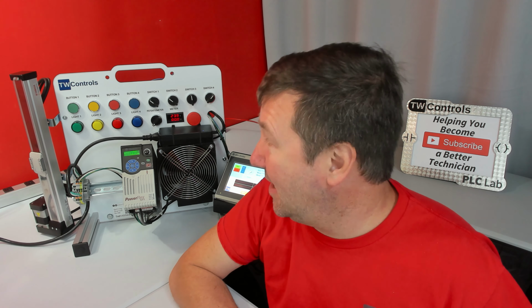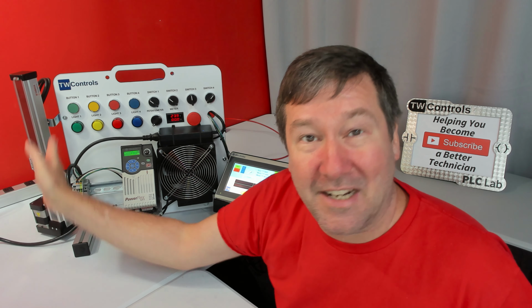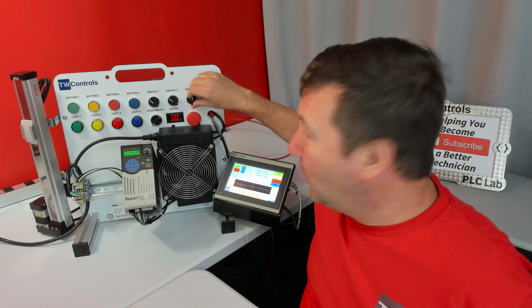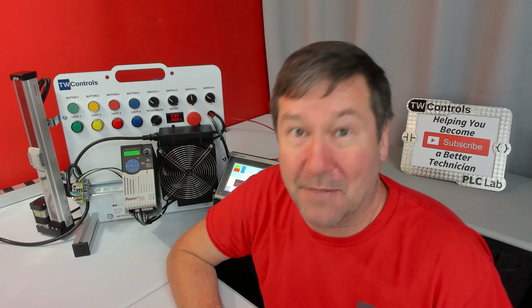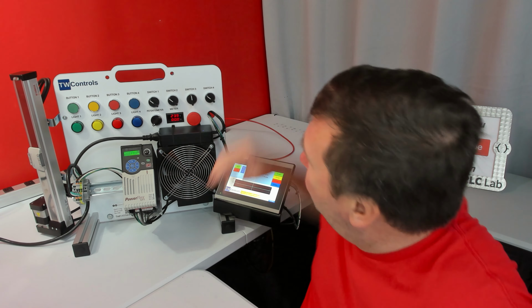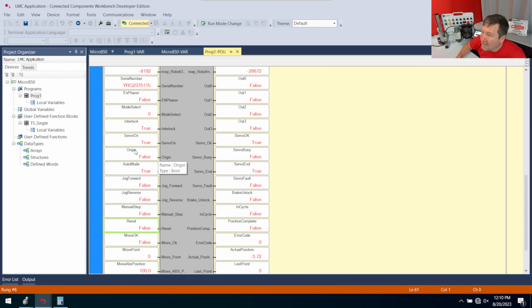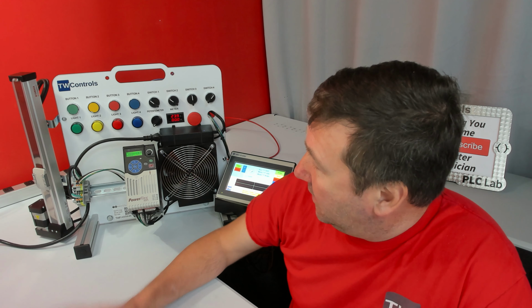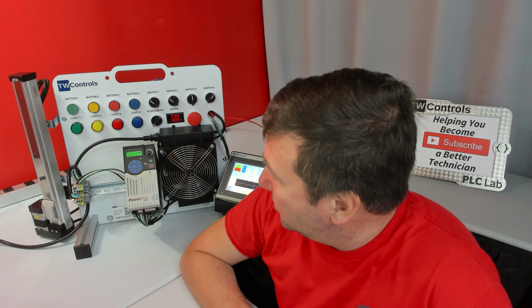And the reason for that is, if you recall when you were setting this up, you had to plug the battery in. So this servo does not know where it's at right now. It's gonna let you put it into hand and jog forward, jog reverse. But if we want to actually do position control, then we're gonna have to home it. So I'm gonna switch 4 to the right to put it in auto mode. And then we're gonna right click the origin and toggle it. Then it'll go down and it's gonna home at one end of the actuator.